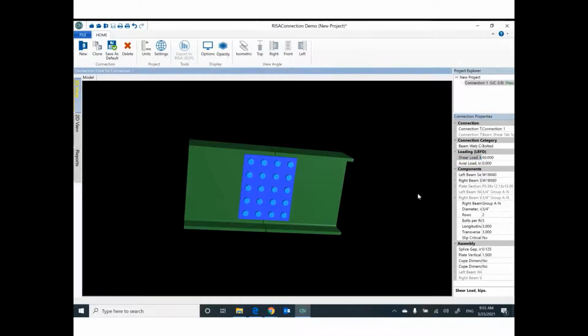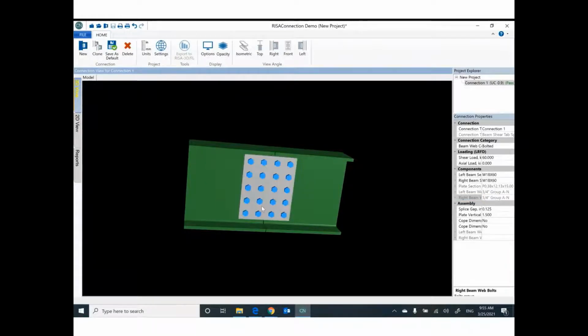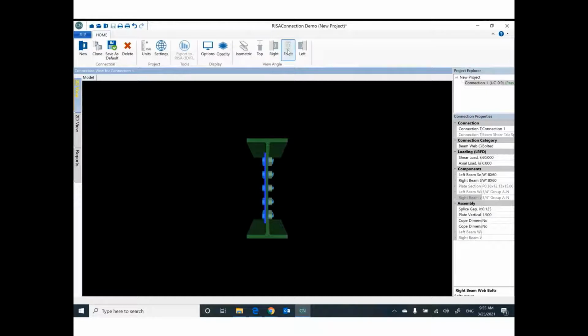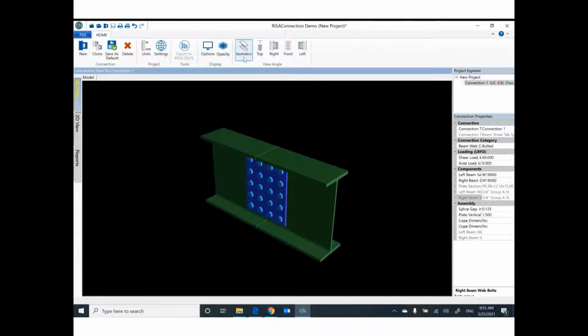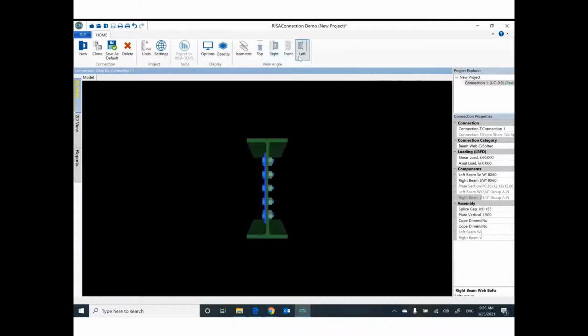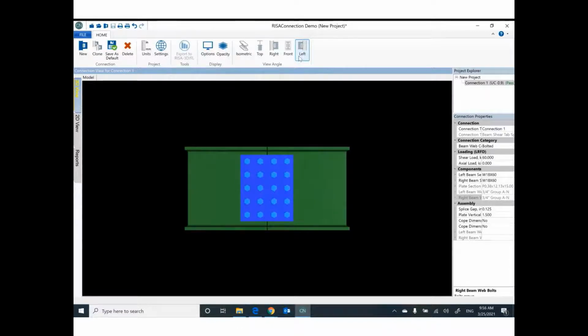So what we learned today, until now, is that we have a connection called a splice connection. You can see here different views, from the top, isometric. These different views can give you everything about the connection. So we learned that we have a connection between two parts of the same beam. In structural analysis this is called a pin connection, and it will transfer only shear without moment.